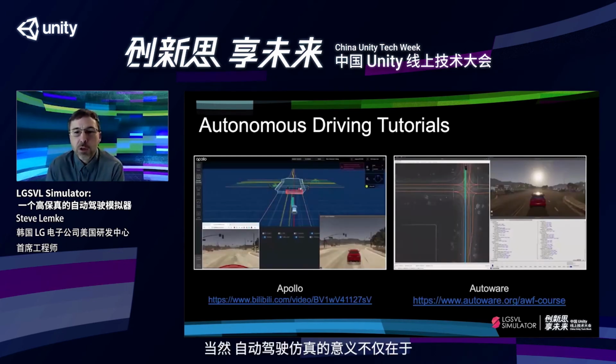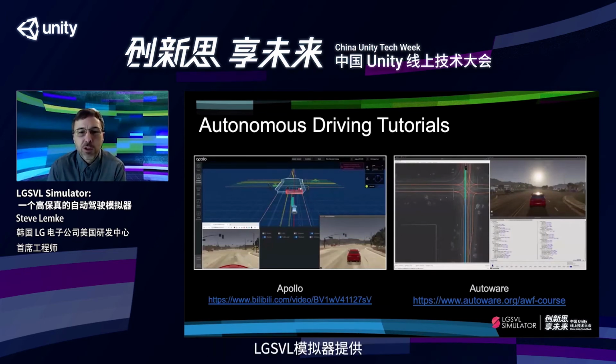Of course, the point of autonomous simulation isn't just to watch NPCs drive around, but to test your own autonomous driving software. LGSVL Simulator includes out-of-the-box support for several open-source autonomous driving software and sensor bridge runtime frameworks. That means we support integration with AD stacks using our built-in support for ROS and ROS2, as well as CyberRT, and we provide everything you need to work with both Apollo from Baidu and Autoware.auto, as well as Autoware.ai.